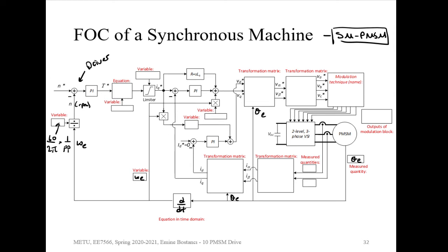From the space vector modulation, from the torque, we know that torque equals 3 over 2 times pole pair number times flux PM times IQ. To get the IQ, we can just divide the torque by 3 over 2 pole pair number flux PM, so that we will get the required current IQ. The variables we need are the pole pair number and flux PM. And if it's not a 3-phase machine, we also need to know the number of phases, but assume it's a 3-phase machine.